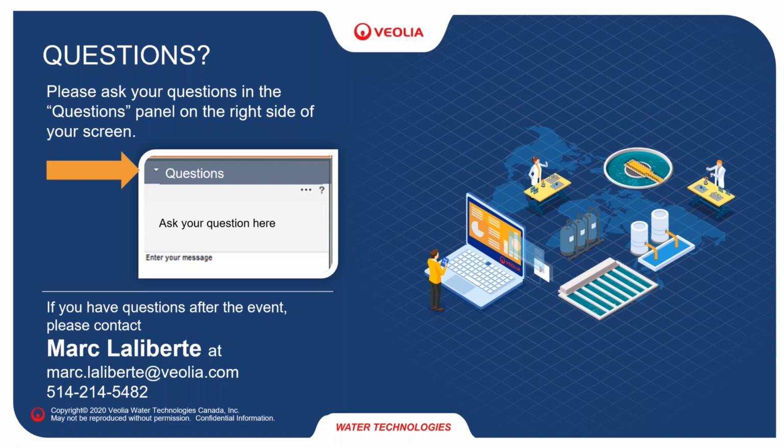The reason why we do try to have sludge circulation is that it significantly improves the removal efficiency. When we do sludge recirculation, we're artificially building up the concentration inside the reactor. So even if the concentration in the influent water is low, we'll simply increase the recirculation. If the concentration becomes higher, we'll simply decrease the sludge recirculation. So with the sludge recirculation, we're making sure that the conditions in the reactor stay optimal for removal, whatever is happening in the influent.